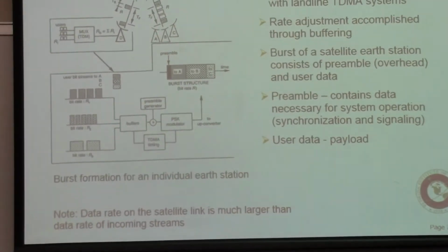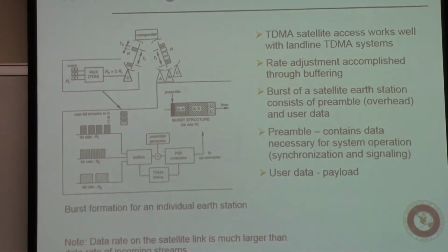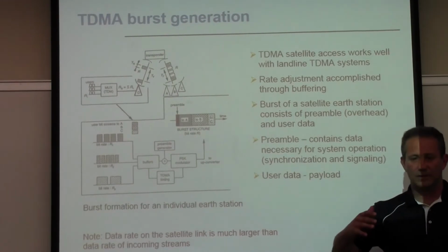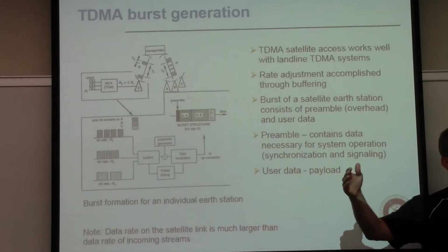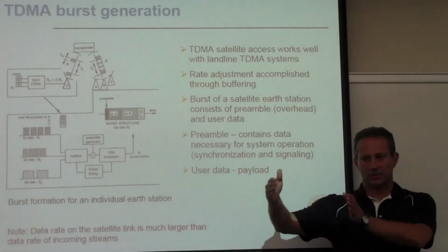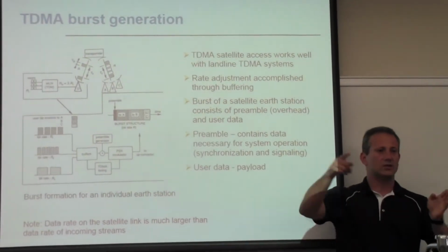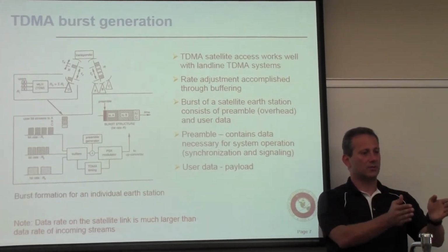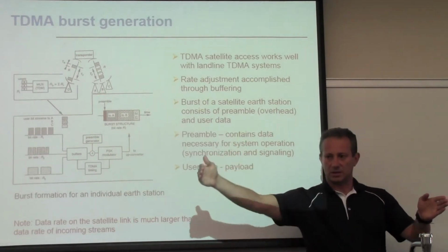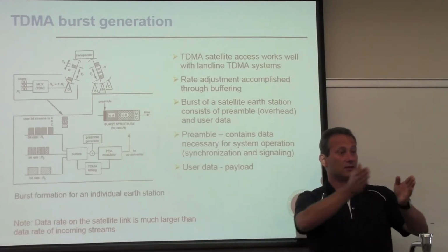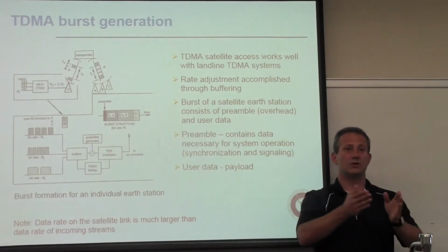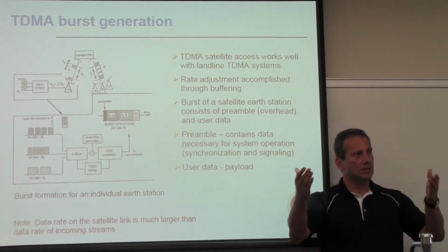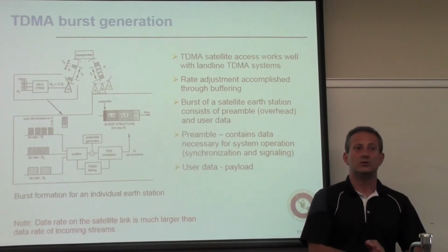This is a little bit more detail of how this is done. The communication here, you have to think about time in time slots, right? So you have time slots allocating. One cycle through allocation of these time slots makes a time frame. So if you look at Earth Station 1 being allocated a time slot, when Earth Station 1 comes on its next turn, the time in between those two is called a time frame. And usually you have n time slots in a time frame. If you allow n Earth stations to be in the access, then n time slots would constitute a time frame.